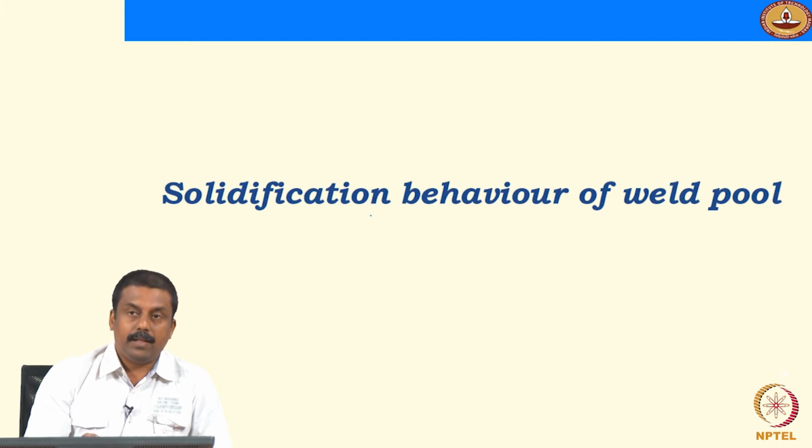Here the actual solidification microstructure evolution was captured using a high temperature camera, which is known as laser confocal microscopy, where we impose a weld thermal cycle onto a liquid pool, and we observe the solidification behavior of a weld pool with a chemistry similar to dual phase steel chemistry.